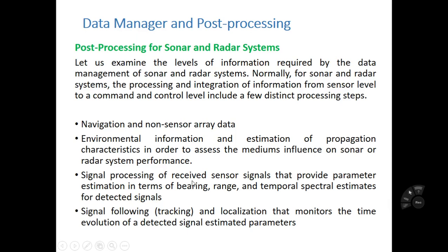Then signal processing of received sensor signals that provides parameter estimation in terms of bearing, range, and temporal spectral estimates of the detected signal. And then finally signal following or signal tracking and localization that monitors the time evolution of the detected signal's estimated parameters.